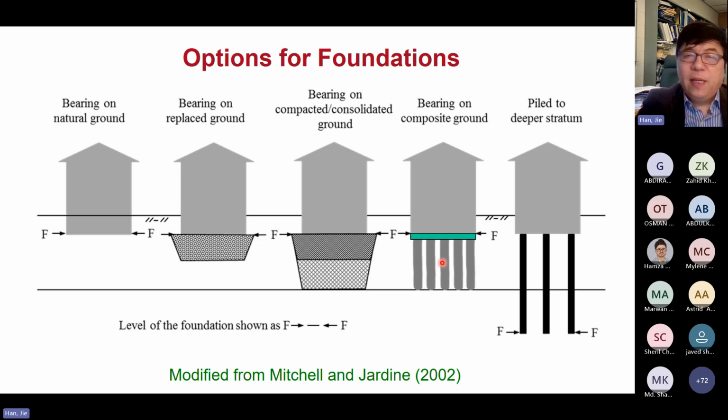And the next option, if the soil is very deep, then you may install some kind of column. And then on top of that, typically you have a cushion. And the columns, you can have different types. That's what I will talk about today, including the rigid inclusion technology. Of course, you can use another approach, a pile foundation. So you may use a very long pile, and basically the pile will carry the whole load. That is typically a more expensive approach than the other approaches.